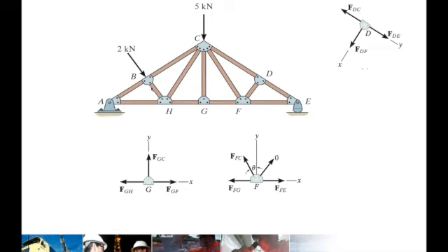So let's say in your design, you want to cut some costs. So you don't want to put member BH. And then suddenly there is an unanticipated 2 kN load that occurs. Maybe there is a cat or a dog that went up your roof. So this is your roof truss. Then you have a 2 kN load there. So if you don't put member BH, then there is nothing that will compensate for the external load.